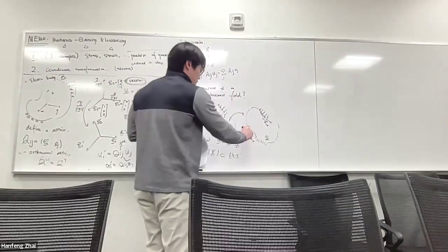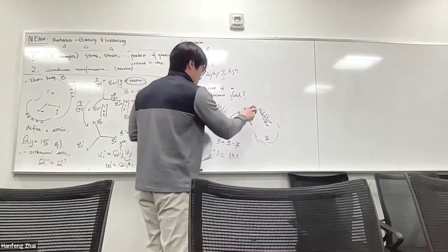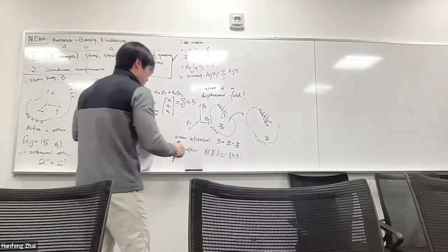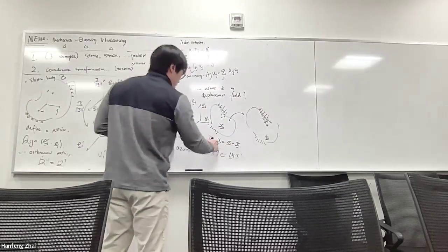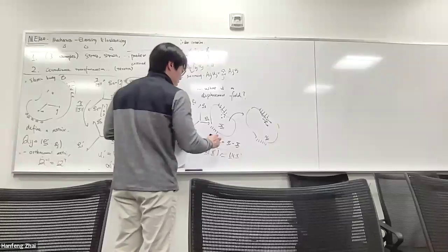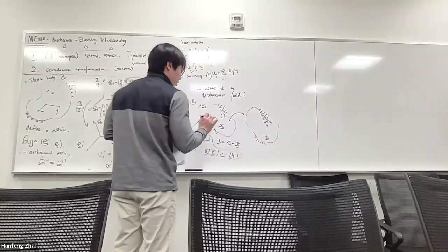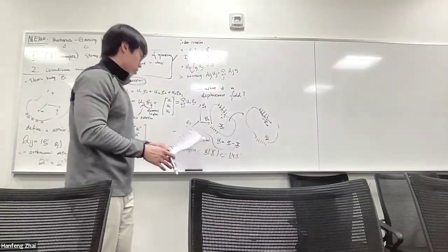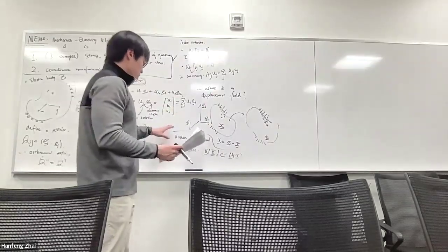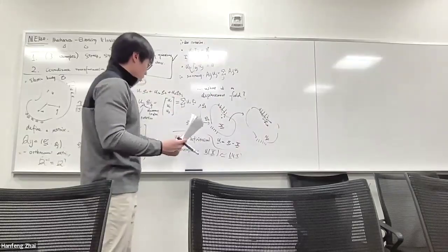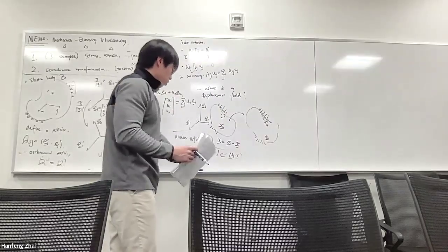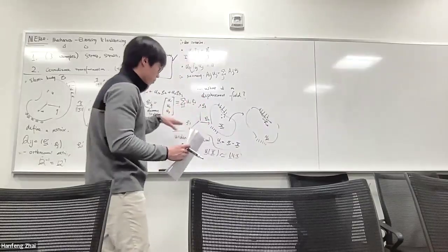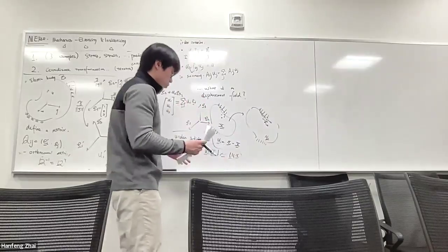Then you have a new vector that represents all the points in this material, which is little x, and the displacement field is defined exactly as the difference between the current and the reference configuration, which is little x minus capitalized X. But for the sake of this class, under the infinitesimal assumption, there is no difference between the two configurations, which are still under the same coordinate system, the same basis vectors. The displacement fields are approximately the same.